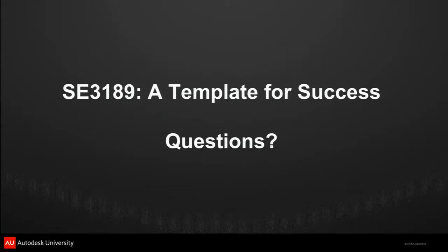Can you customize the view name as you put it on a sheet? The view title. It uses the last one that you use. Well, yeah, but starting out, I don't have that set up in my template either. It's not something that I have set so that it customizes. You will pick the last one, but not the last one, the last one that was saved in the template. Yeah, there you go. Just the in-the-box. So in your template, if you threw a view onto a sheet and set it as a specific view type, when you started a project off that template, every time you threw that same type of view onto a sheet, it would have that view type.